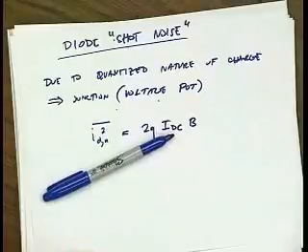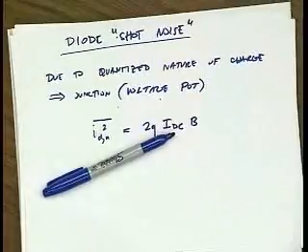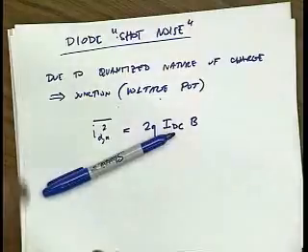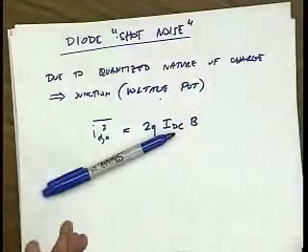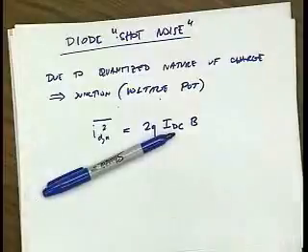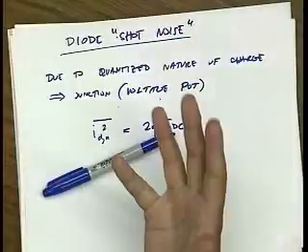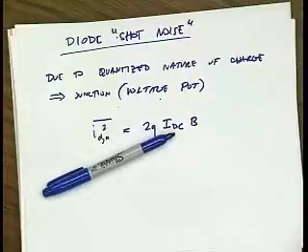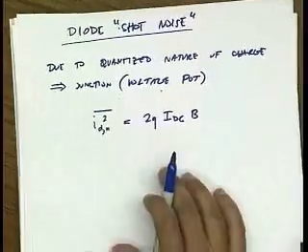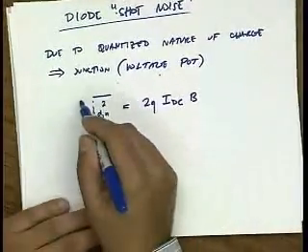And even if you put a bucket out and you watch the water level rising, it's going to rise at more or less a constant rate, right? That's the DC current. But the water drops are arriving randomly. So they actually also make a nice sound on the roof. Kind of a noisy sound, right? And another example is snow on your television, right? You listen to a channel that doesn't exist, you hear that noisy sound. A lot of this is just related to random arrival time and the discreteness of charge. Okay? So this is the shot noise. It's very important.